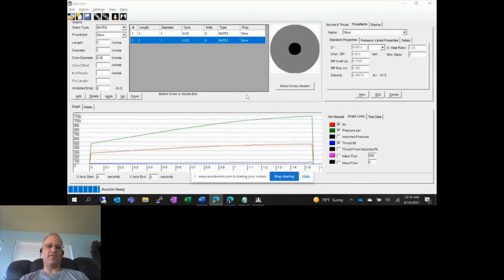For those of you going into the field and having access to some of this equipment in college, we'll probably get some hands-on with that potentially, and that's cool. For someone like myself who's a hobbyist, that kind of equipment is a little bit out of our reach. But there's a second method, often called a ballistic test motor, which is basically a large, heavy-walled end burner motor that will burn essentially a piece of propellant shaped like a hockey puck.